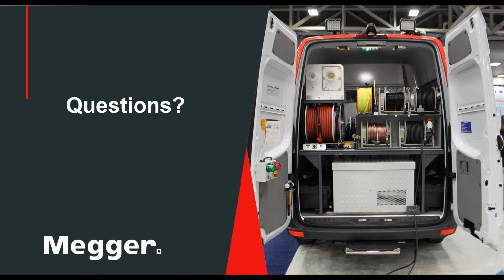So that has not much to do with the fault locating, unless you have a low voltage cable. Low voltage cables in Europe are typically not armored. So you have no shield and you don't have an armor. So basically you do fault locating phase to ground.